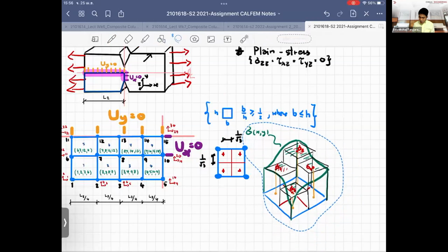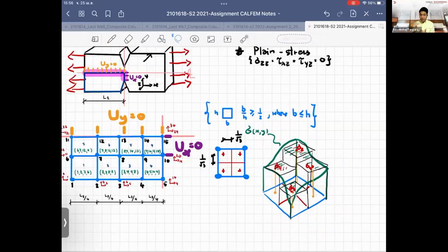So when we want to fit the graph, the idea is that the more Gauss points, or points of representative stresses in the element, that we have, the better the results you have, right?